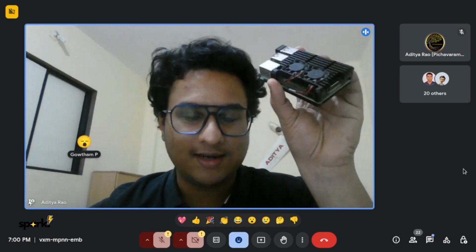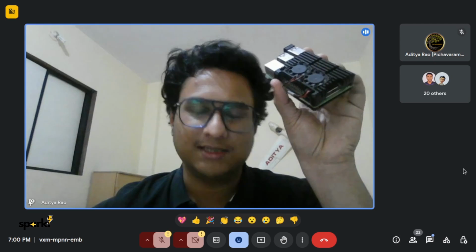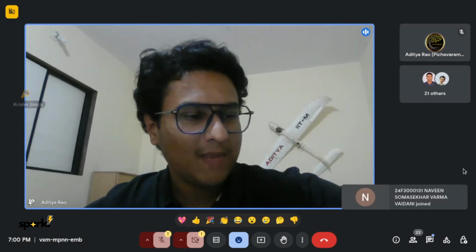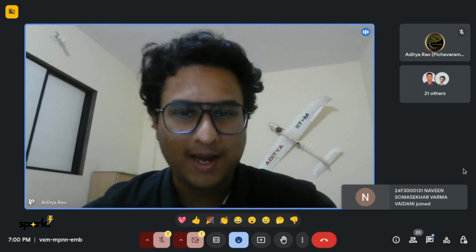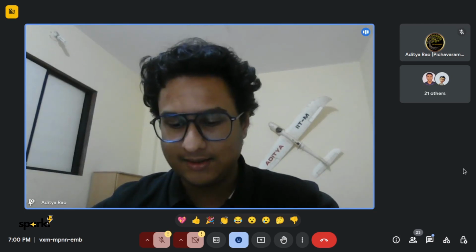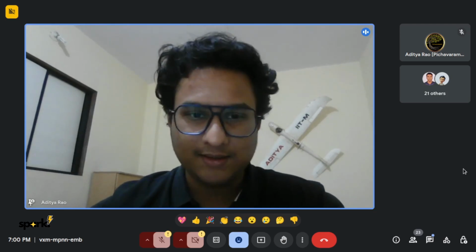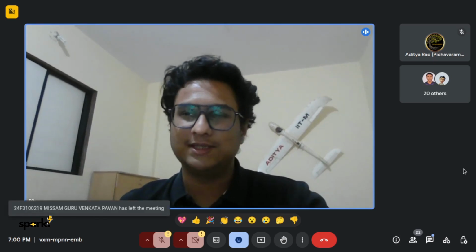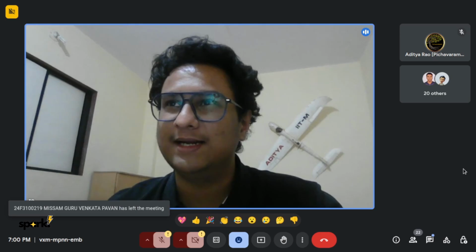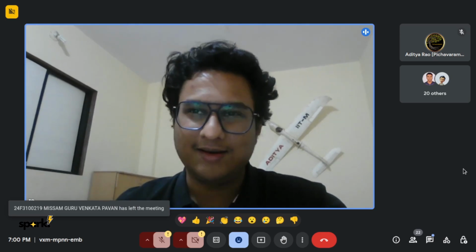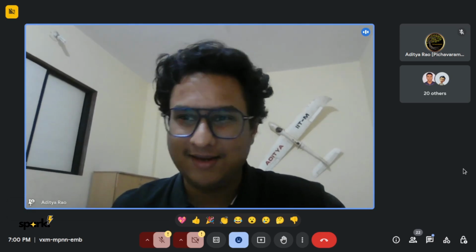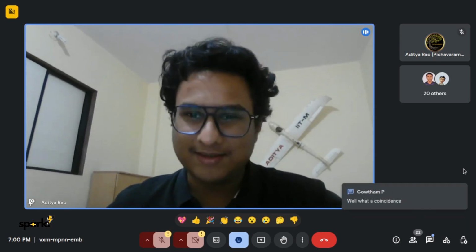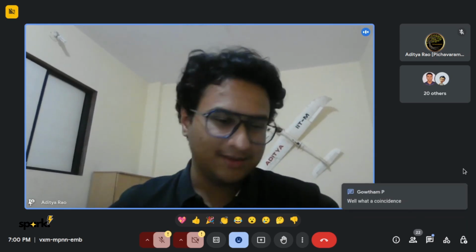As soon as it detects that the moisture has gone below a certain threshold, it triggers the water pump for a certain duration depending on the moisture level. The moisture sensor collects data every 5 minutes on summer days and every 10 or 15 minutes on winter days, because obviously during the summer things dry out sooner than on winter days.